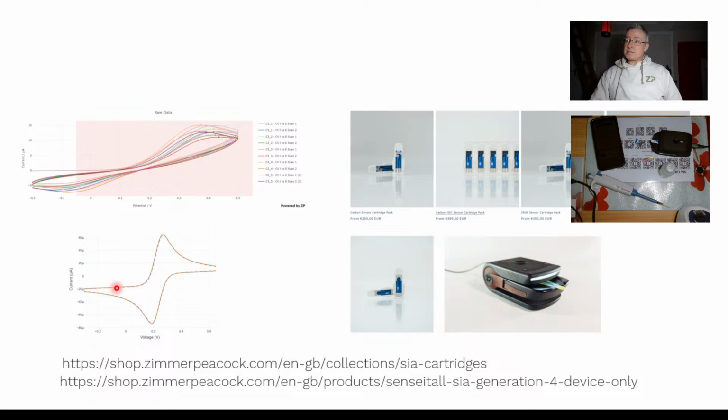If you're expecting something that looks elegant and beautiful like this, and you actually get something that looks like this, and as I say, we checked to make sure that the resistance of the tracks on the screen printed electrode weren't particularly high, and they weren't, then it probably comes down to the connection.